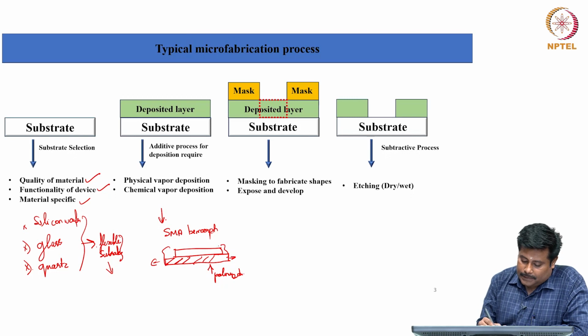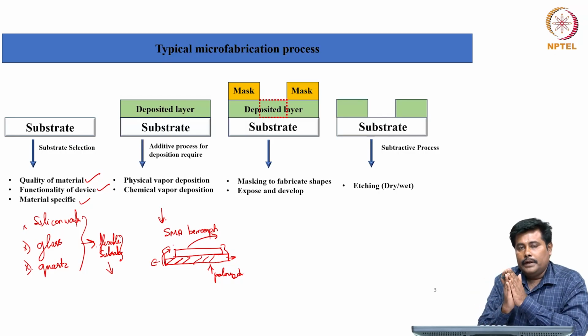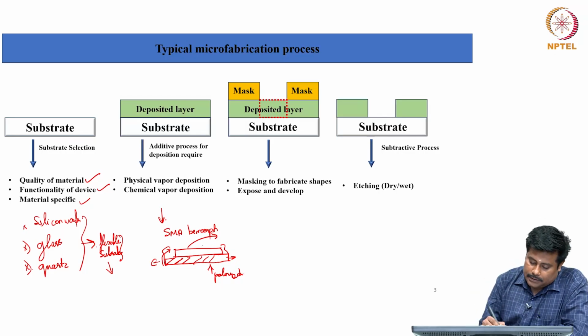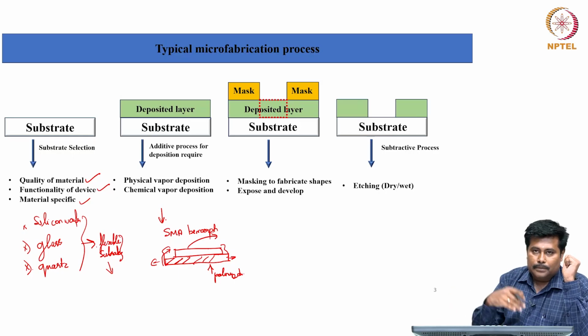When the SMA gets actuated in a particular direction, or with a particular displacement, the polyimide will also try to take the same shape. That is, when we actuate the shape memory alloy there will be a deflection, and when we cut off the actuation, it comes back to its shape.